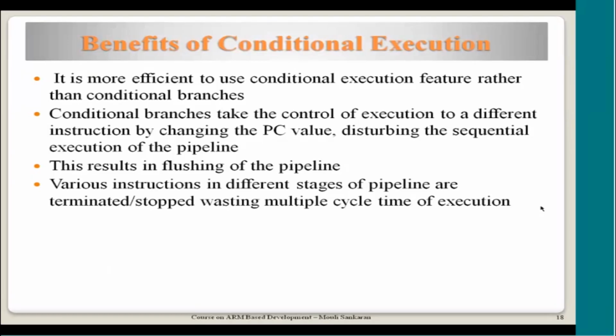So that you understand that when an instruction is executed, it is in the execution stage of the pipeline, and the next two instructions in the memory are already in the pipeline. One is in the decode stage, and the other is in the fetch stage.